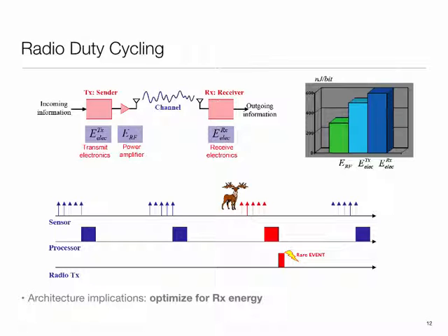Now, if I adapt that, typically what will happen is my sensors will collect the data at a periodic rate, let's say, for 1 second. They're going to buffer them up into some area of memory. The rest of the system wakes up, does a DMA, pushes it to a radio, and things go out. So it directly affects the rate at which I'm sampling, and therefore directly affects the quality of the model I'm getting, or the quality of classification or control or whatnot.